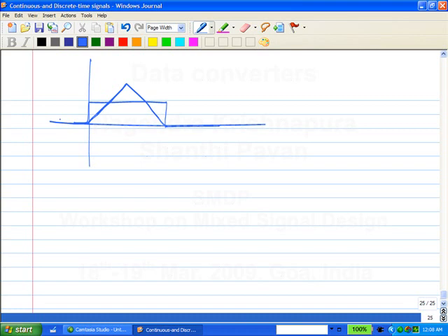So clearly, the rectangular window modified the signal in some way. Although the shape inside was the same, it introduced abruptness. Now this one is not introducing abruptness, but it's modifying it in some other way. We have to see exactly what the modification is. If we see that, then we can figure out whether it is acceptable or not. There are obviously an infinite number of choices for windows, right? We have to see which is acceptable, because we are clearly modifying the signal in some way when we take the finite number of points. Right now, our primary goal is to minimize leakage. So if we satisfy that goal and the signal is not corrupted in some profound way, then we'll accept it.